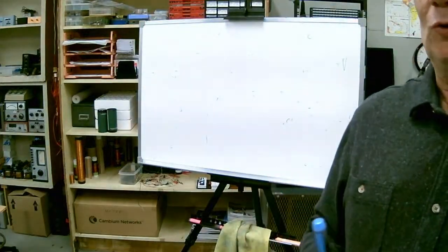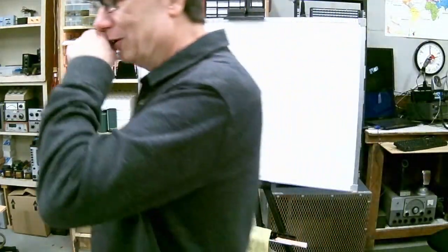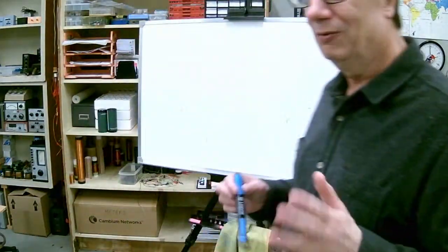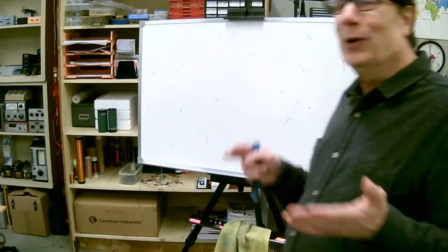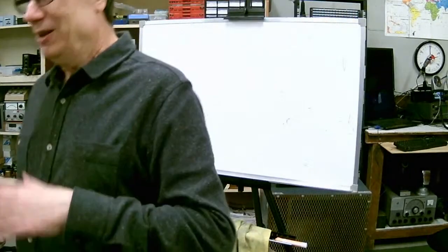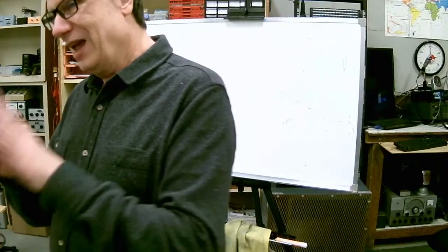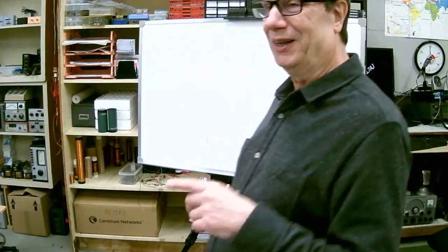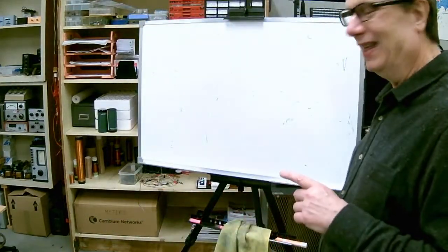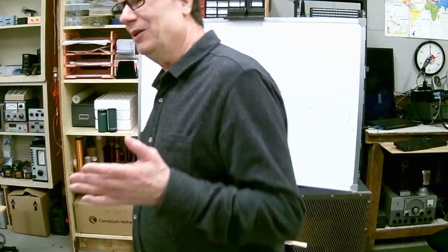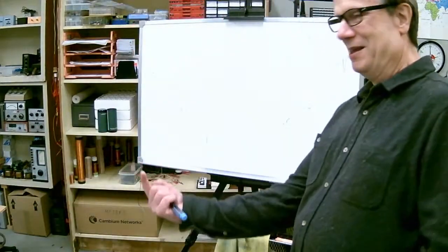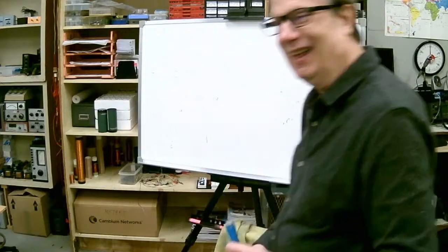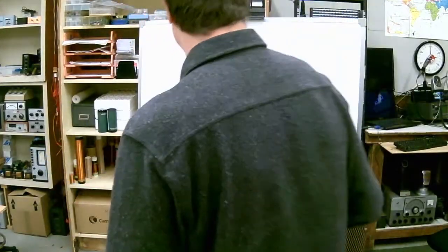And so to make it a little more user-friendly, we had to make some modifications. Even nowadays, there's nothing more sensitive than a regenerative receiver. It's not even in theory. You can't even get better than that. Because not only in theory, but in practice, at the verge of oscillation, it's got infinite gain. And it also has infinite Q. It's infinite selectivity. Pretty cool. But again, you pay the price. The price is being able to balance something right on the edge.